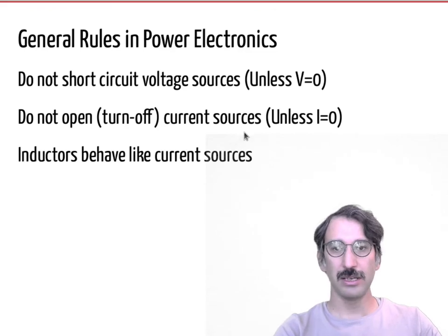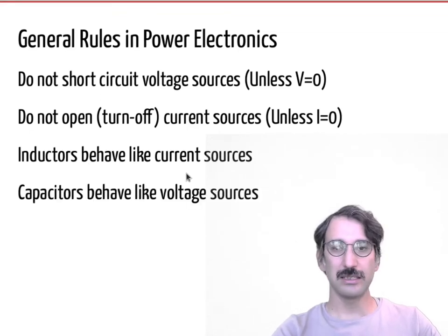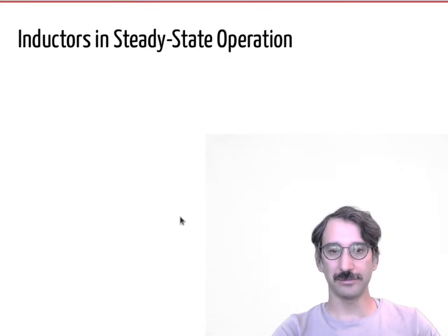In the same relation, inductors behave like current sources, and capacitors behave like voltage sources. So you don't want to open circuit an inductor while it is carrying a current, or short circuit a capacitor while there is a voltage stored in it. Okay, so let's have a look at inductors in steady state operation.